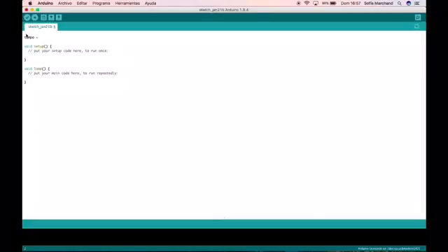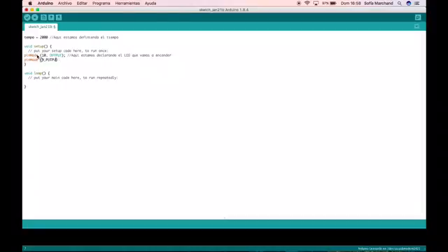First, we have to declare a variable for time. Then, in void setup, we have to declare which LED we're going to turn on with pinMode. It is important that we declare it with the function OUTPUT because it is going to turn on. In void loop, we have to declare when the LED turns on and turns off.